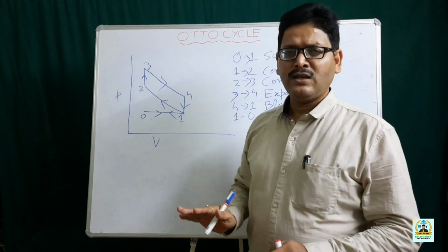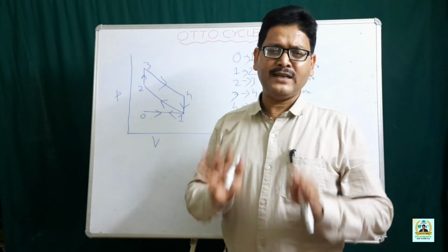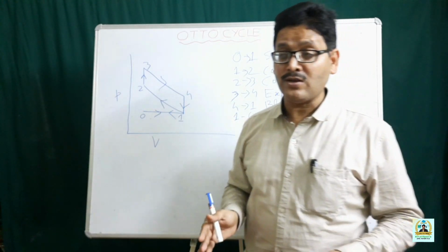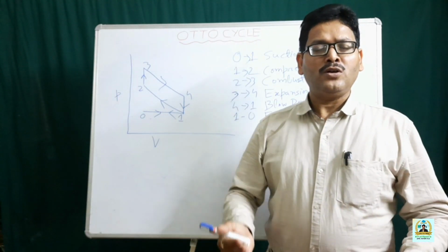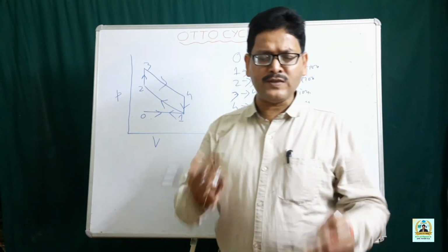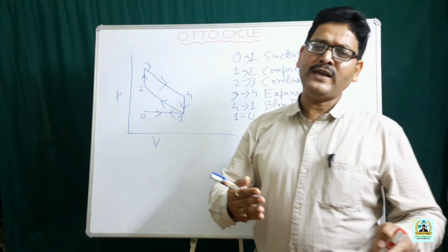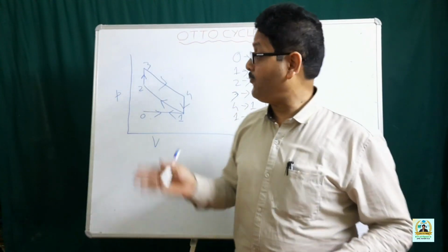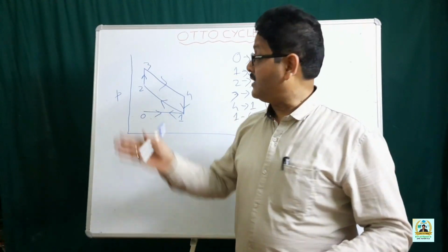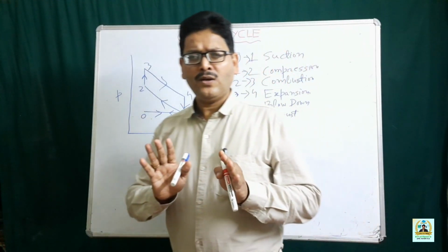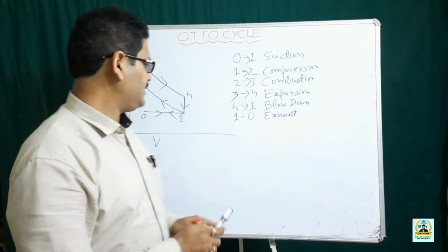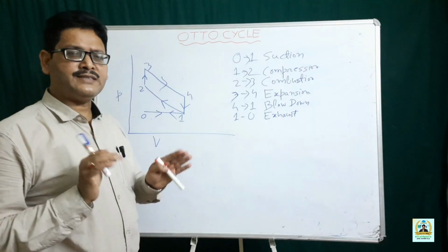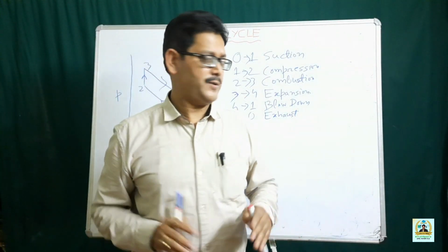Here we consider that it is drawn in at atmospheric pressure and the exhaust is also taking place at atmospheric pressure. But to draw a finite amount of working substance into the system or to remove a finite amount of working substance, you require an infinite amount of time if the pressure remains the same. But for the time being, you simply remember that both the induction, that is suction, as well as the exhaust are taking place at atmospheric pressure.